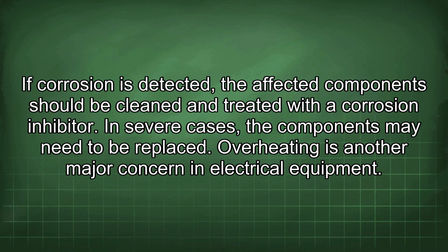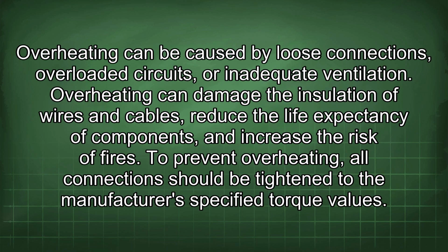Overheating is another major concern in electrical equipment. Overheating can be caused by loose connections, overloaded circuits, or inadequate ventilation. Overheating can damage the insulation of wires and cables, reduce the life expectancy of components, and increase the risk of fires. To prevent overheating, all connections should be tightened to the manufacturer's specified torque values.